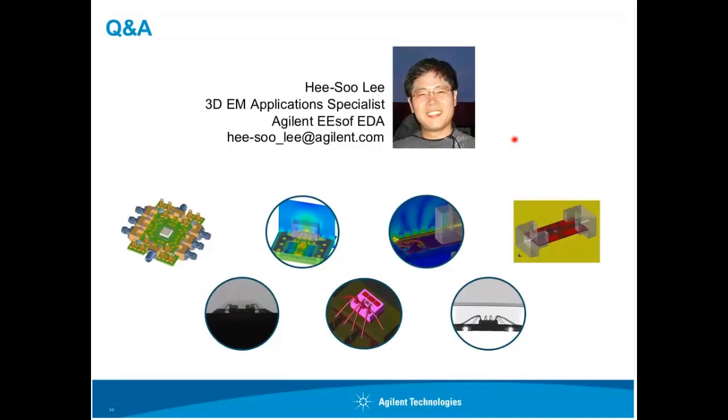From Saqib, is there any way we can design circuits using shielded coplanar waveguide lines in the ADS environment? Shielded coplanar waveguide lines. From my understanding and knowledge, that can be done through the substrate stack-up definitions. Instead of making the top side open, you can set the boundary conditions to closed boundary, representing top side and bottom side closed. And then you'll be able to just create those coplanar structures and simulate it.